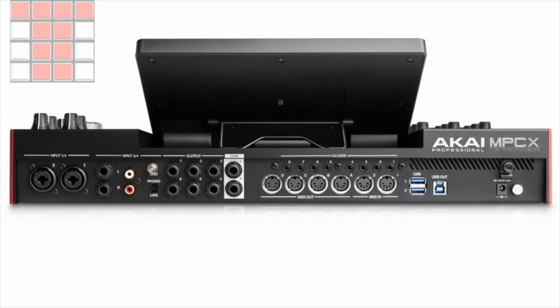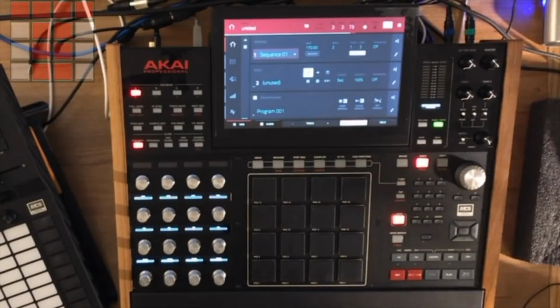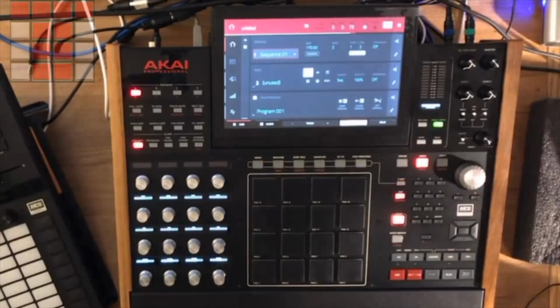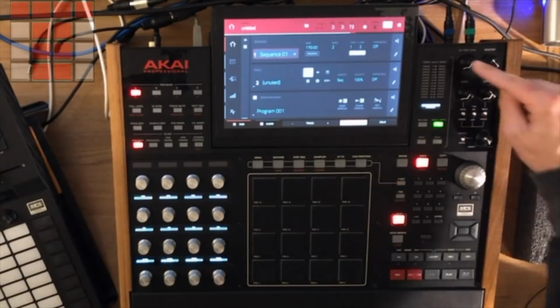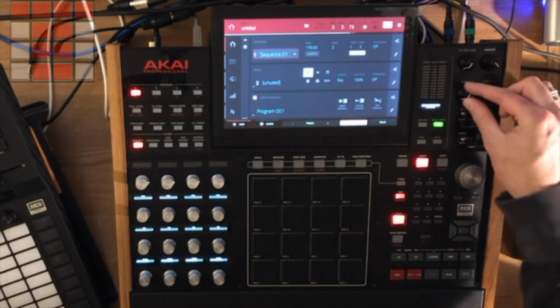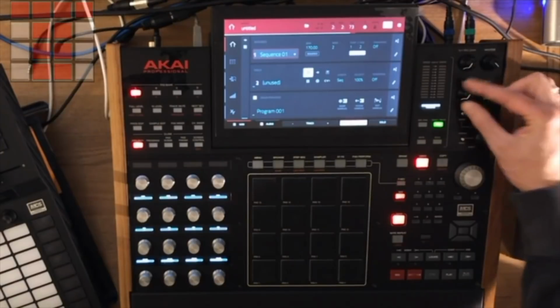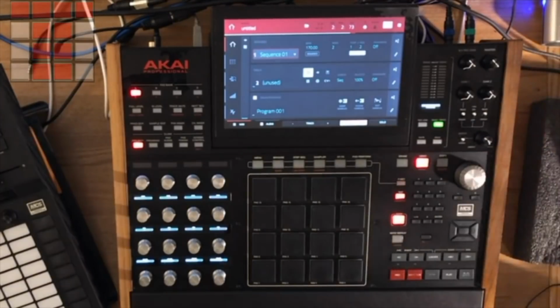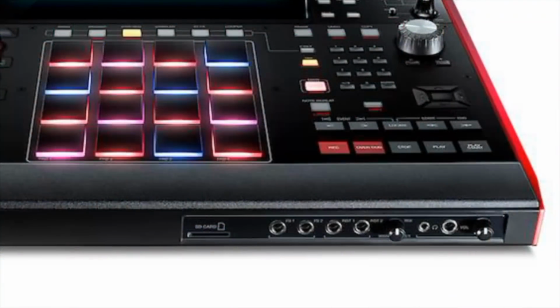So let's go back to the main view, or the top panel again. That is what the 3/4 gain knob does. It controls your inputs 3 and 4 gain, and these two knobs can increase the gain of inputs 1 and 2, which I've just shown you are the main combi inputs. But they also control the front panel audio inputs, which are called the instrument inputs. They are the two 1/4 inch jacks you can see just to the left of that knob.